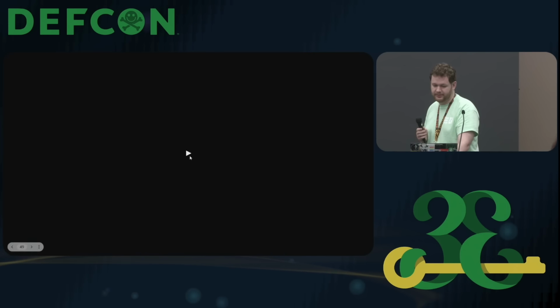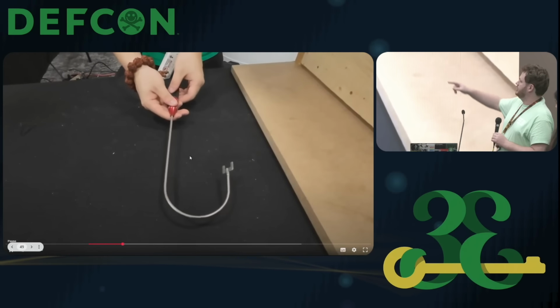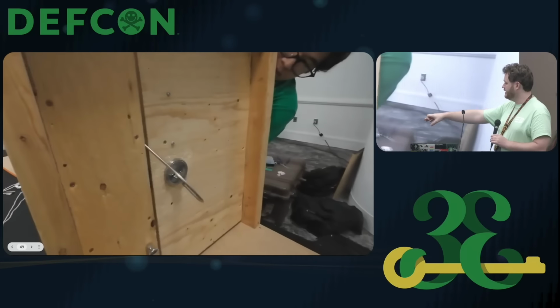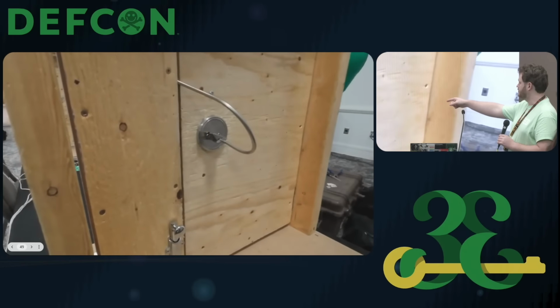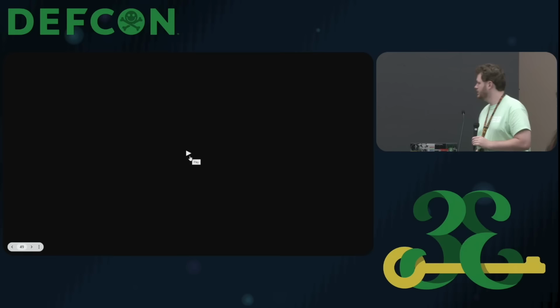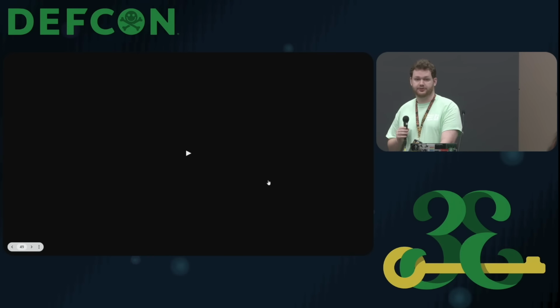Then we have another video demonstration right here. We love those around here. This is the turning of the tool down at the back right there. You turn that little clawed end right there, attaching it to the lock themselves, and then you turn that black tool at the bottom again, and you can see the deadbolt turning and being able to be pulled forward. So it's very simple, but again, it requires the space requirements to have that tool be inserted.